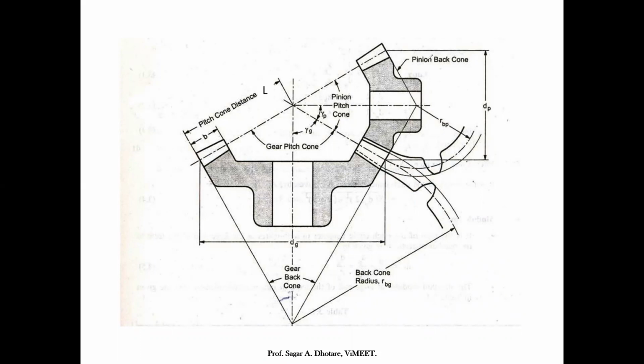The pitch circle radius of this imaginary spur gear is equivalent to the back cone radius, and the module is equivalent to the module. The practice of characterizing the size and shape of bevel gear teeth as those of an imaginary spur gear appearing on the developed back cone corresponds to what is known as Tredgold's approximation.